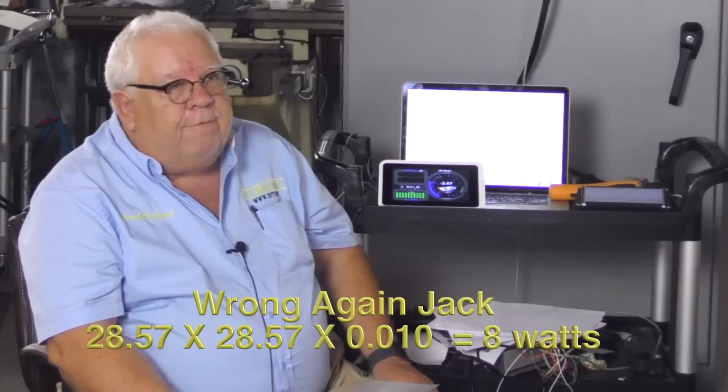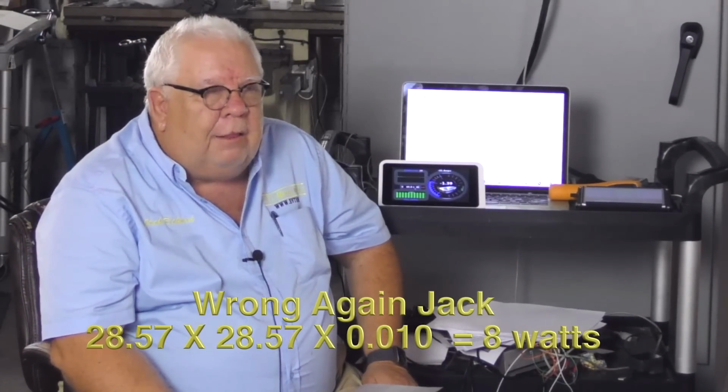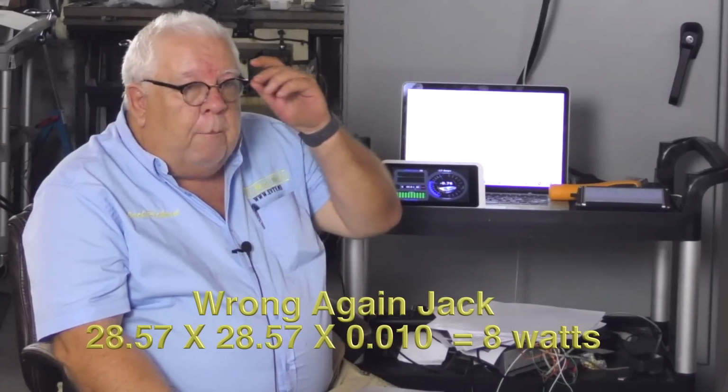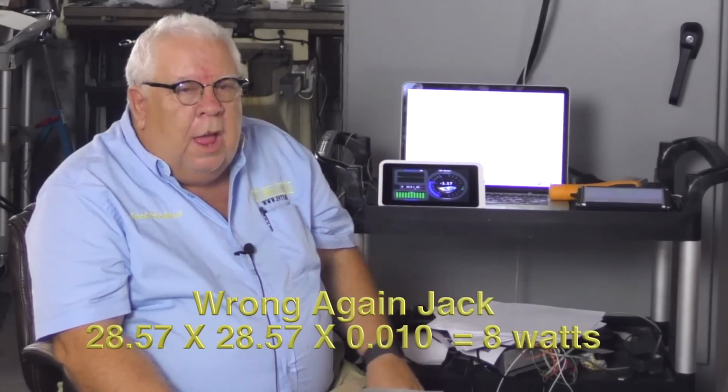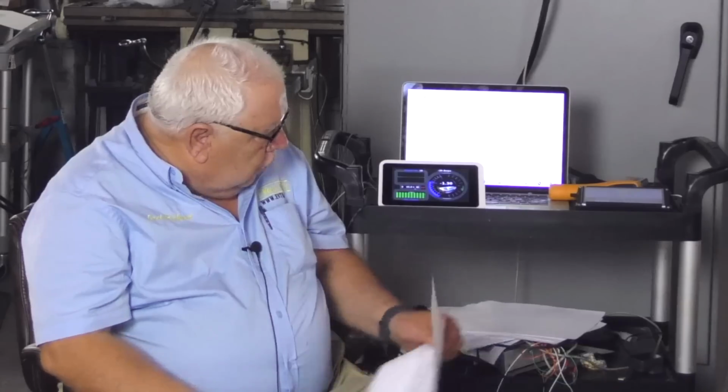So the much higher voltage is a huge ally in having much lower currents by an order of magnitude. And that order of magnitude is squared in calculating heat losses. And this is why I don't really advocate 48-volt systems for solar energy storage.